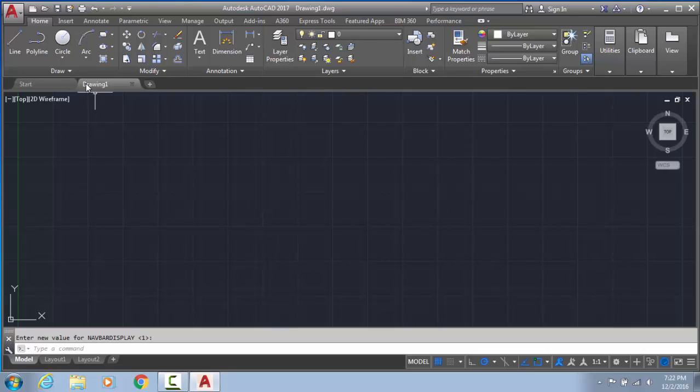For example, if you have to make a line, you will move the cursor from here to here, click Line and then start making. Instead of doing that, if you press L and space, your line starts already. So you can save a couple of seconds in every command. If you are going to be a professional user, you should use the commands. Not for all, but a dozen or 20 commands you will need. After using them sometimes, you will already get them by heart.